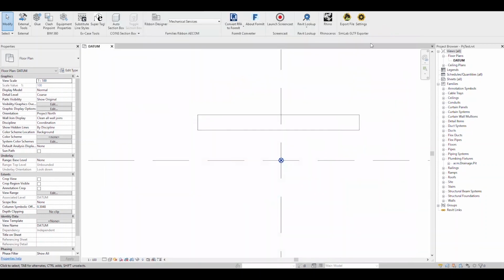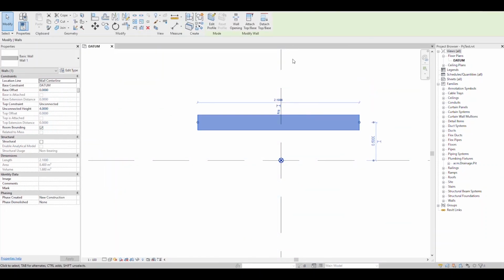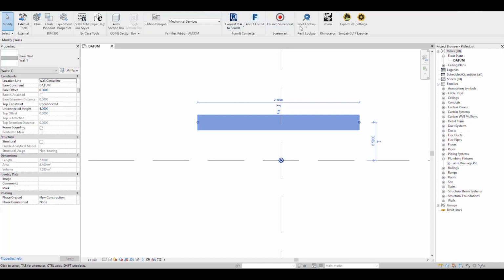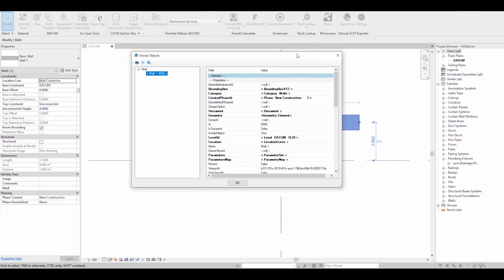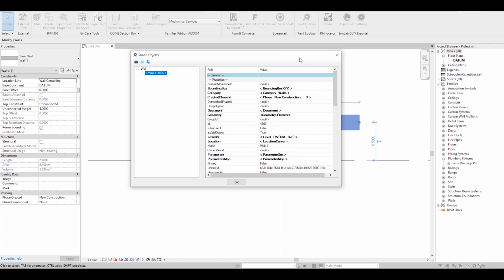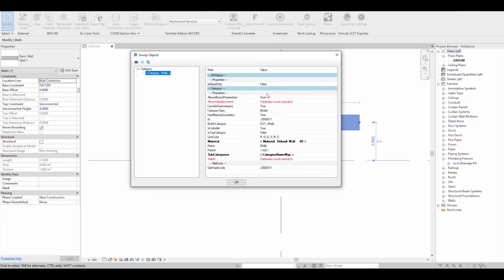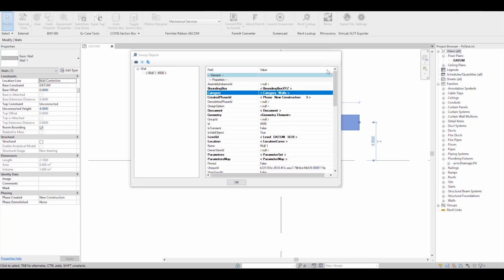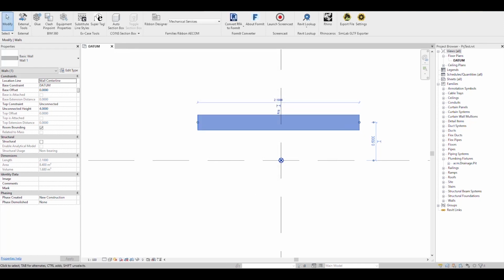Again, if I go back to the object, I'm always going back and forth using the Revit lookup because it's the way I've learned, and I think it's the best way to query the object within the project. So if we go back here, we can see that the wall, the name of the category is built-in category OST walls, which is exactly what I'm using in the script, really.